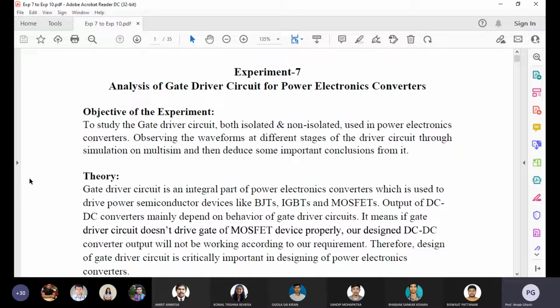That is your actual signal, and it is not so big. It is a small nominal voltage; for example, if 100 volts is coming, you may get around 2 volts. So there is scaling down of voltage as well as isolation. That is input side isolation. Then we analyze that voltage by comparing it with the reference voltage, which is the set point voltage. Suppose your set point voltage is 12 volts; that should be the actual output voltage.